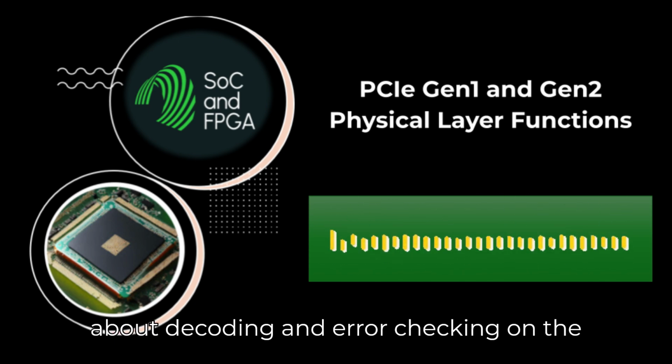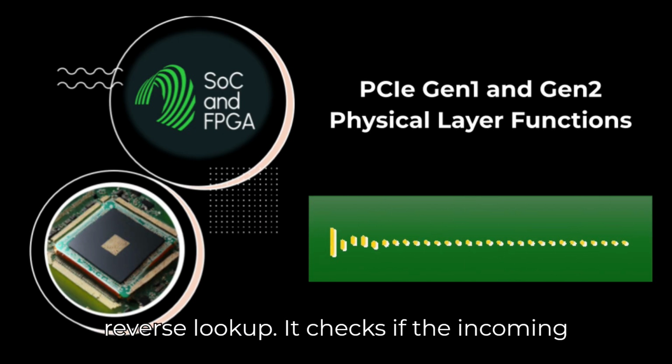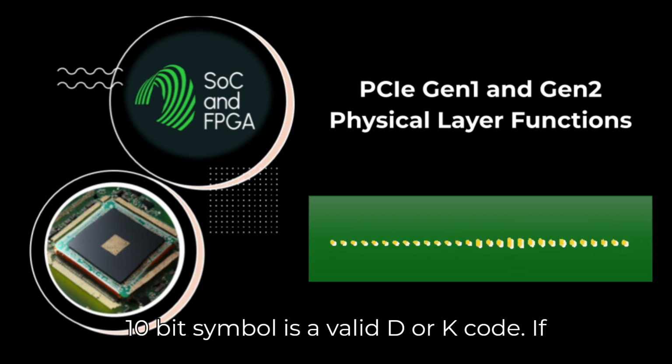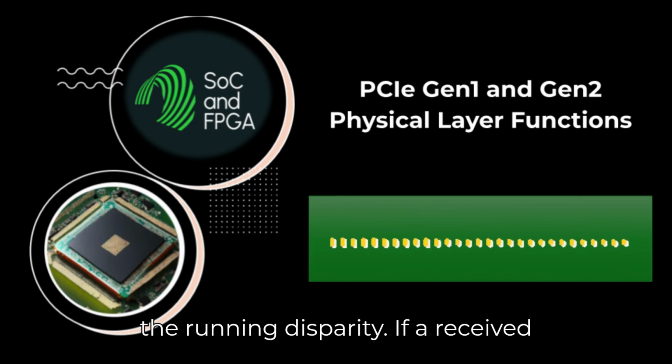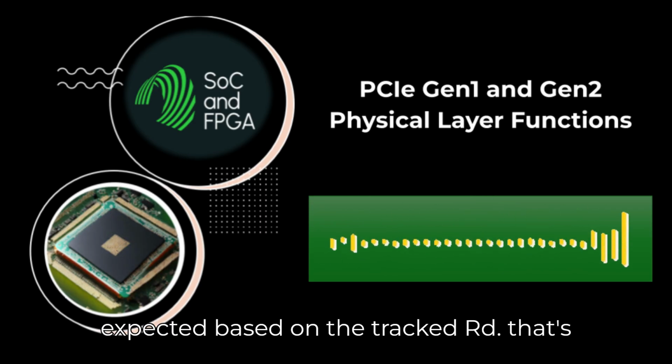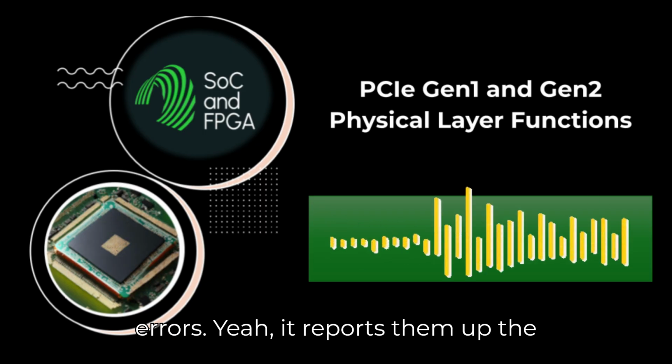What about decoding and error checking on the receiver side? The receiver does the reverse lookup. It checks if the incoming 10-bit symbol is a valid D or K code. If not, that's a code error. It also tracks the running disparity. If a received symbol's disparity doesn't match what's expected based on the tracked RD, that's a disparity error. And it flags those errors? Yeah, it reports them up the stack.